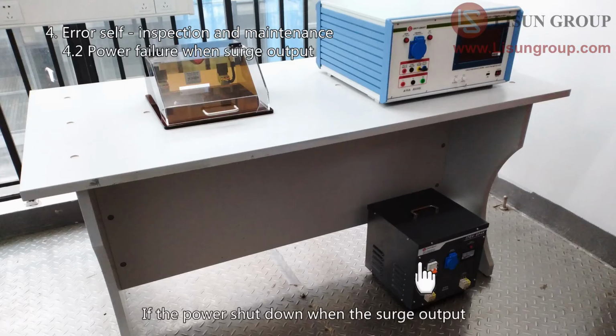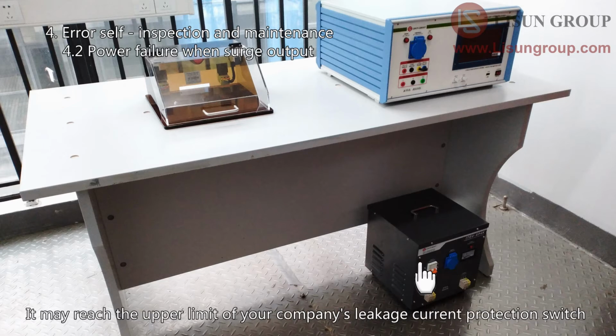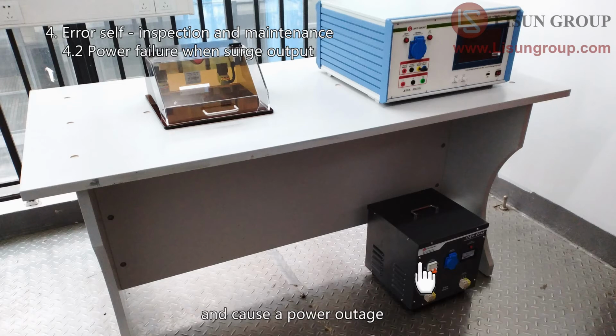If the power shut down when the surge output, please confirm whether an isolated transformer is used. An instantaneous large current pulse will be returned during the surge test. It may reach the upper limit of your company's leakage current protection switch and cause a power outage.